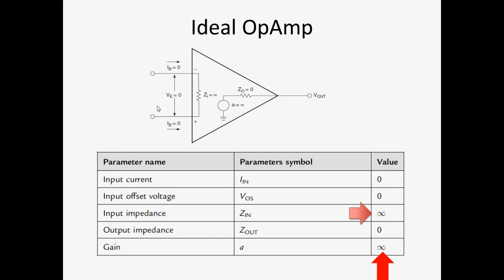And now you might start to understand things. Contact impedance of electrodes, input impedance of amplifiers. The input impedance of the amplifier is not something you can control. It's been given to you. And probably you can go and check your equipment. One of the specifications that they declare is the input impedance of the amplifier, which is in the order of gigaohm or teraohm, of course, but the contact impedance is in the order of hundreds of kiloohm.